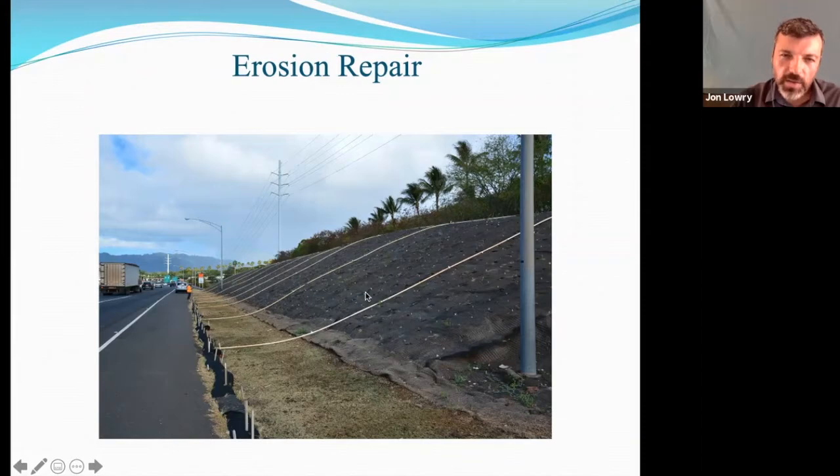You can also see little holes cut out for them to plant the native grasses. They're like grass plugs that will be installed at those sites. At the base of the slope here, we have hydromulch that has a native seed mix, and that's also going to be part of the permanent BMP. But this fiber roll at the base of the slope is a temporary BMP.